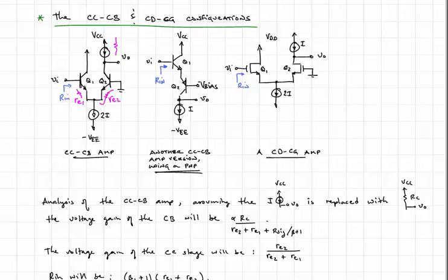operating point for this amplifier is VI being equal to whatever the base of Q2 is, and it's grounded in this case. So when VI is equal to 0, the currents are splitting evenly, and we can think about that being the operating point. That's unique from any of the other amplifiers we've looked at in the past, because we've always had to bias up the base or the gate of a transistor.